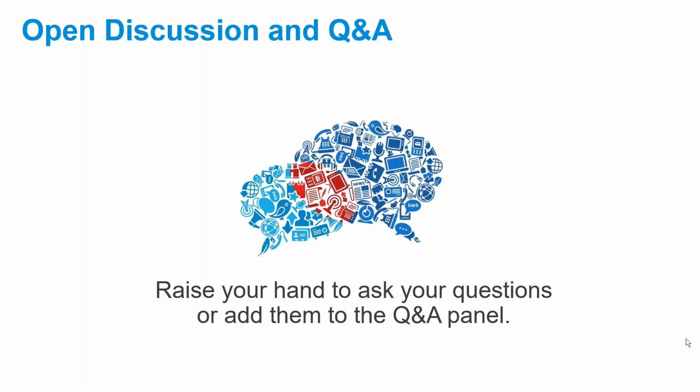because that's one nice thing about this too that collaboration brings, is all your plant models live in the cloud, and the Chrome-based web browser can go in there and you can view these models too. So if you have workflows right now where you're generating NWDs overnight for your engineers who have Navisworks Freedom on their machines, and then they can look at the model, you're actually replacing that now with a browser that can go to the cloud and look at your Plant 3D aggregate model up there.